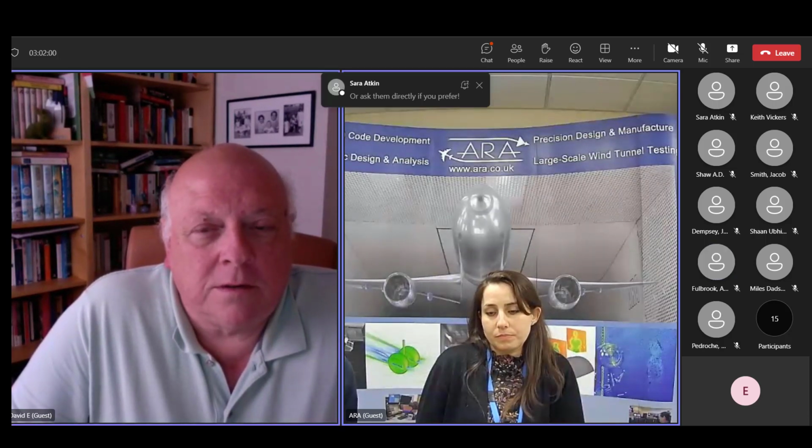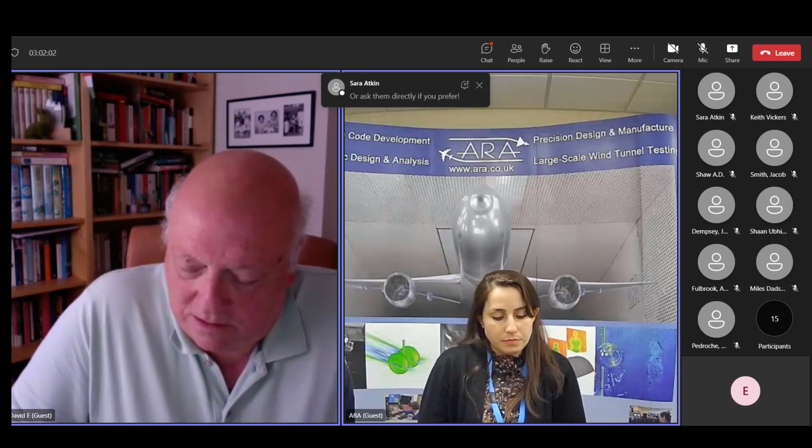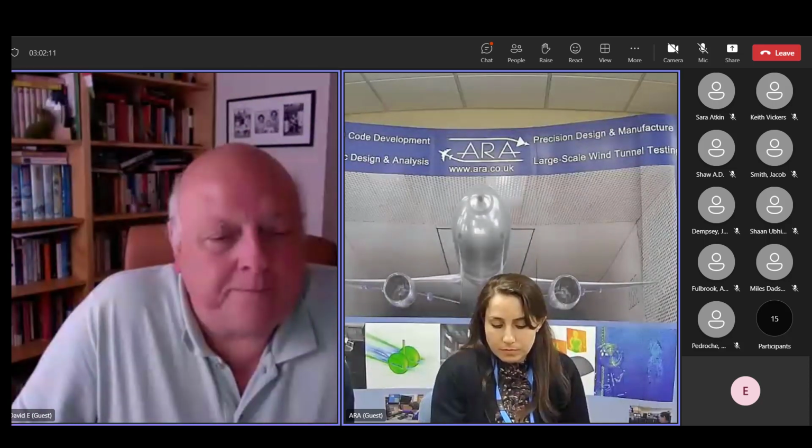There's another question that I'm burning to ask, actually, because it wasn't obvious to me there, the actual load cell that you're talking about there, is that a single axis or is it a multi-axis device? Yeah, sorry, that wasn't really made totally clear. It's 5-axis, so in a way it's 3-axis, so it's measuring axial force, normal force and side force, and then it's measuring the pitching moment and the yawing moment, so 2 moments and 3 forces. So the only thing it's not measuring is the roll effect on the balance. So it's a 5-component balance. We often make 6-component balances. Sometimes we only make 1 or 3-component balances as well. Yeah, depends on the application.